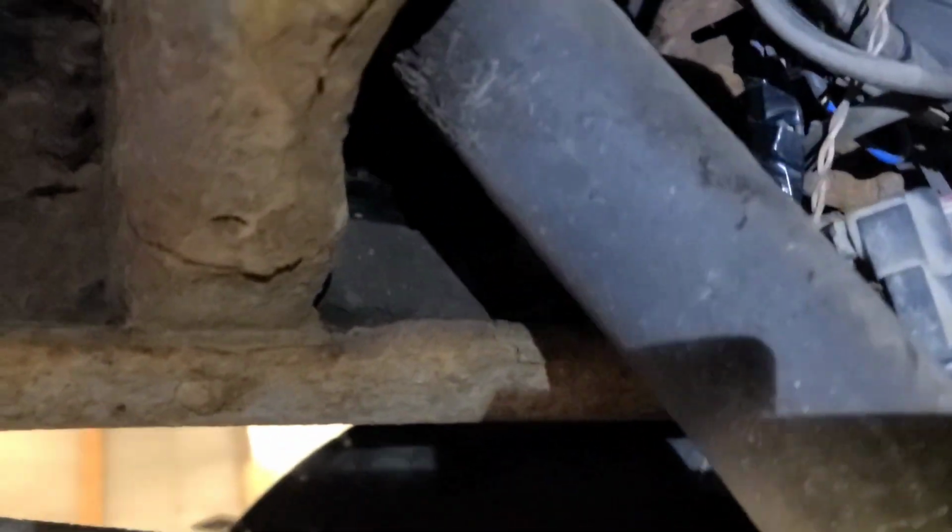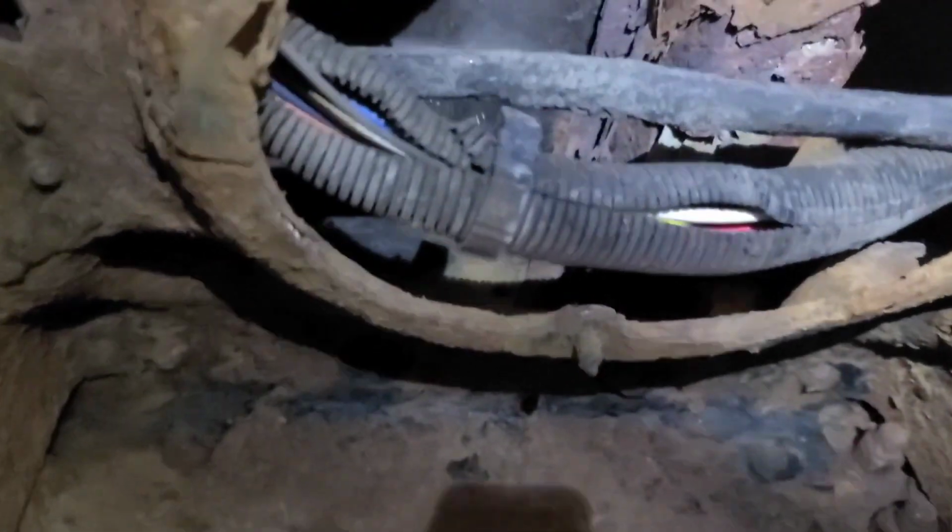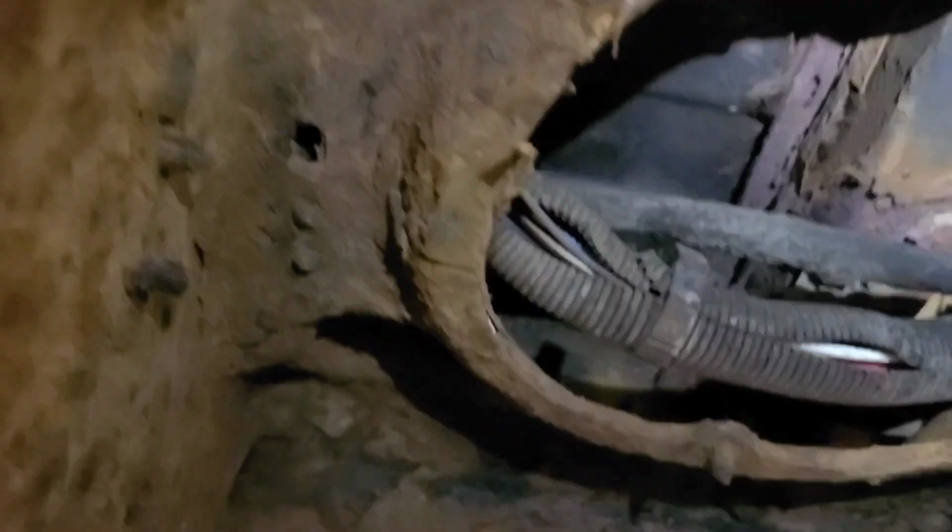Well, that trailer brake controller lives behind the left shock on the frame rail. It's not very convenient to get to. I've got it unplugged and I've got a headlight connected to the red, white wire and black wire, which are power and ground, and it lights a headlight. So now I'm going to jump those two wires over to the wires that go out to the trailer brake plug, because this thing is rusty. There's the wiring harness there, and the plug in there, and we'll check continuity of the wires.